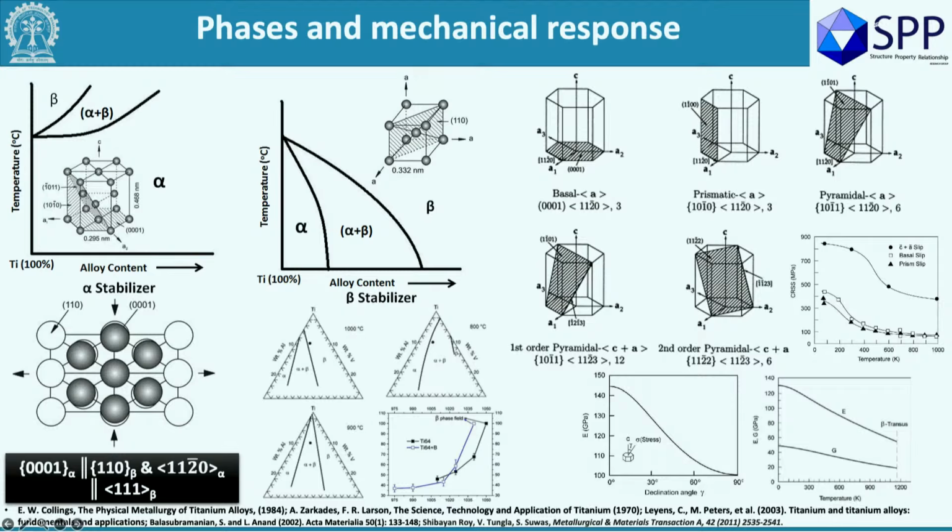Titanium, of course, Ti64 basically, is an alpha plus beta alloy. So what happens? We can change this phase stability. We can tune it. We can add alloying elements, usually heavy elements. We add vanadium, moly, niobium, this kind of heavy elements, and we stabilize this beta at room temperature microstructure, and then we make various types of alpha plus beta alloys.